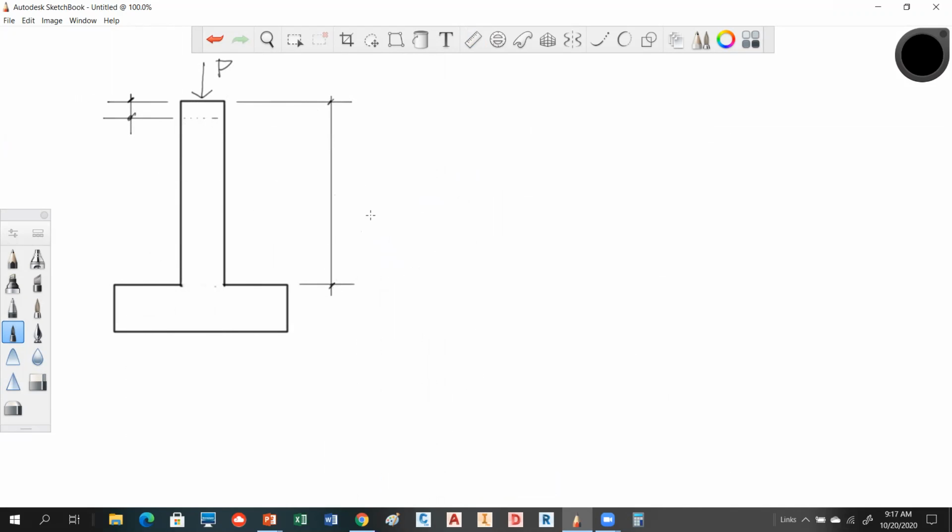So the original length on this column is 10 feet. And the amount of deformation due to the load is 1/10 of an inch, which is actually not much, I guess. This is a concrete object. We know the original length, if we measured this, was 10 feet. We've loaded this with a force P, and because this is compression, it is going to be decreased by 1/10 of an inch due to the load. So notice the units here: inches here and feet here.